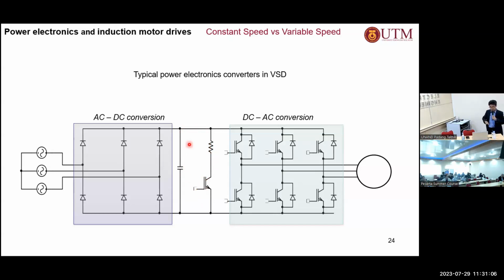This is a typical structure of variable speed drives. A more expensive one, which I think is the ACS 2000 from ABB, uses active transistors at the front end instead of a diode rectifier, which means that the power can go back to the supply. So you don't need the crowbar circuit there. It saves more energy, obviously. If you replace the diodes with transistors, it is called an active rectifier, and the power can actually go back to the supply.